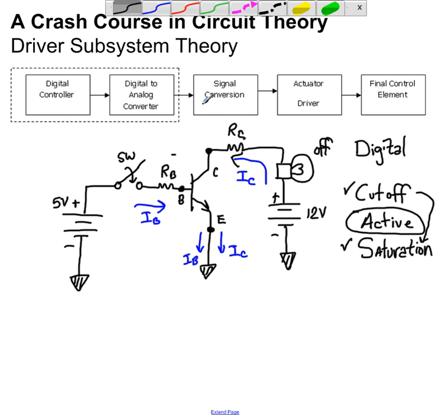What that means, if you do your math, it basically means that if you have 5 milliamps of current over here, then that can translate into 500 milliamps of current over here based on the specifications of the transistor, or even higher. Looking at this, we can conclude that a low current is able to control a high current.